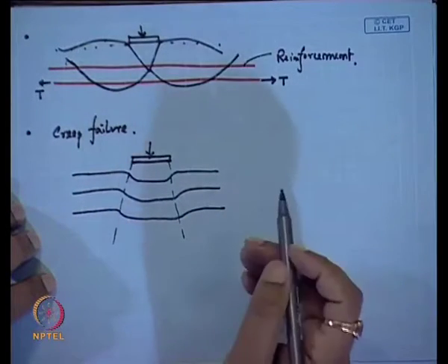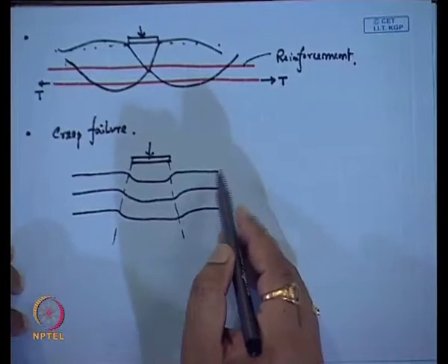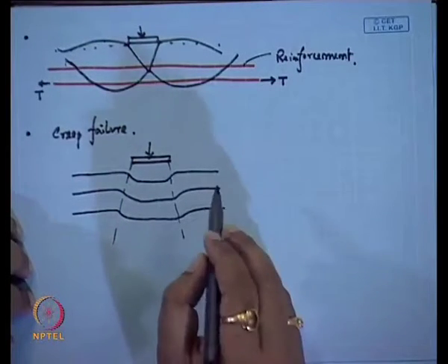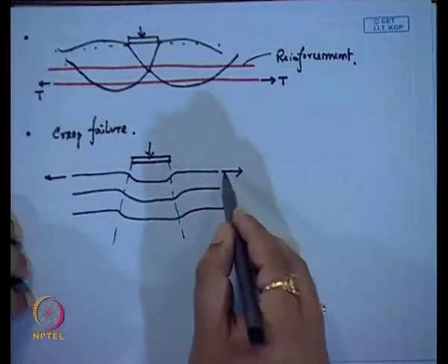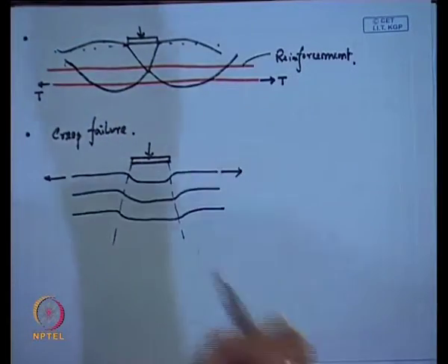against constant stress. When we apply load, tension will develop within the geosynthetic. If this geosynthetic is under tension for a long time, there will be strain within the geosynthetic. One is the vertical deformation of the geosynthetic due to the soil movement. Another is that when the tension is developed, the geosynthetic is under tension, and because of this tension there will be strain within the geosynthetic.